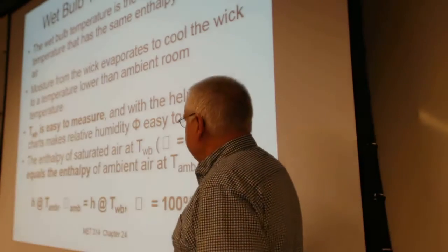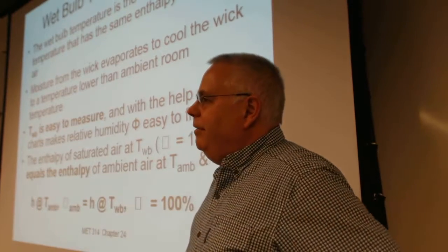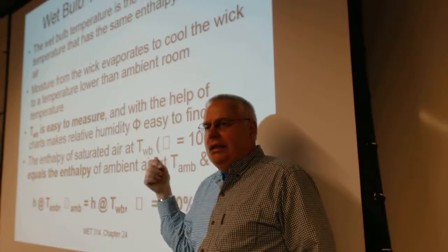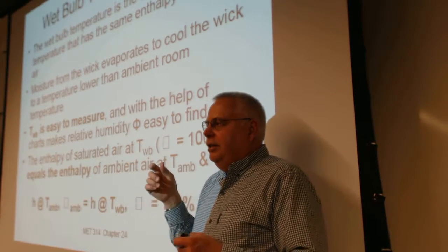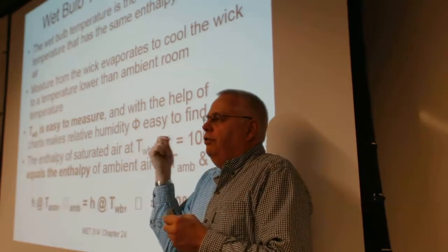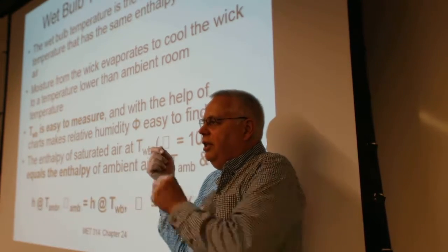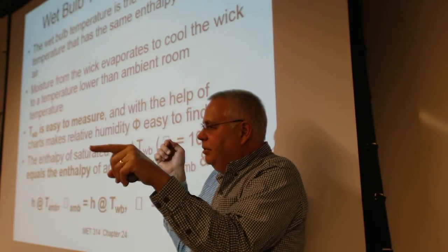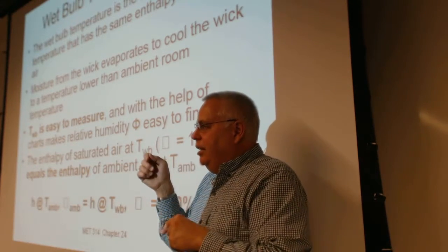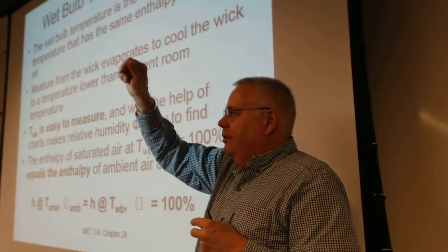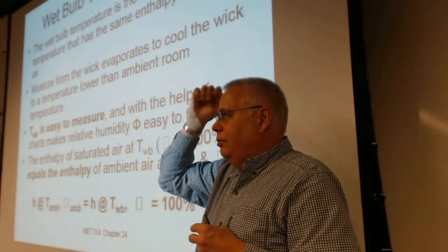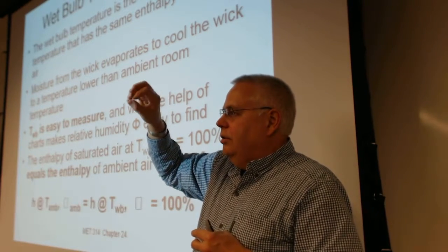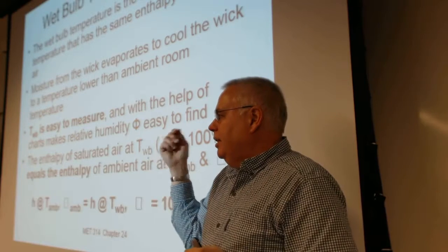And then there's wet bulb temperature. If you take a wet washcloth and swing it in the air, it's going to go to an ultimately low temperature. Now you're taking the energy in the air and you're trying to force it to 100% relative humidity. In one case, you're taking the water vapor and chilling it down until it becomes saturated. That's one temperature. This other one, you're using the energy in the air. With that same amount of energy, what if it was forced to saturation? You take the energy in the air to vaporize. That's what the wet bulb does.